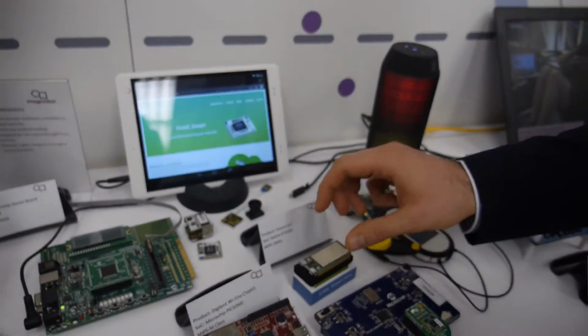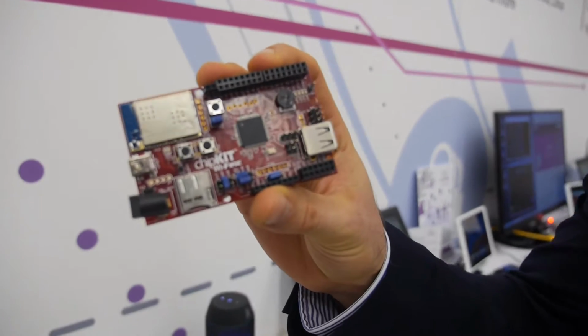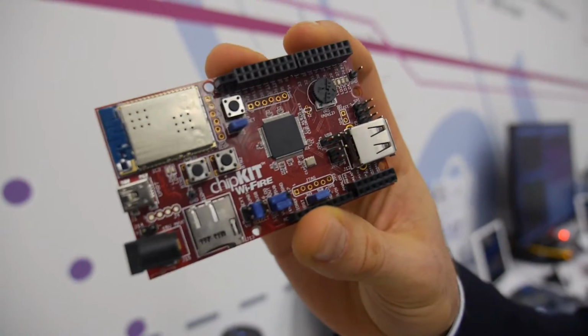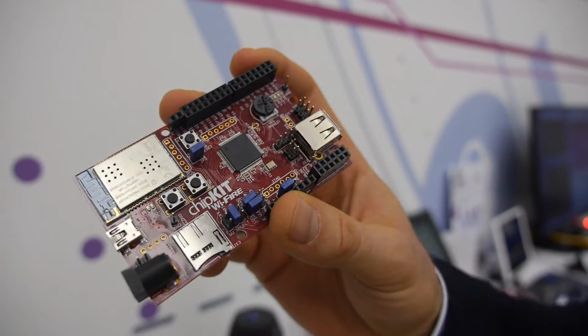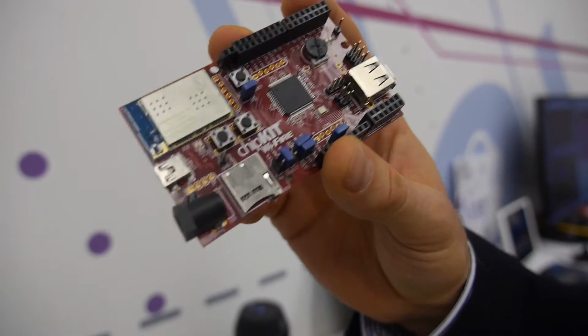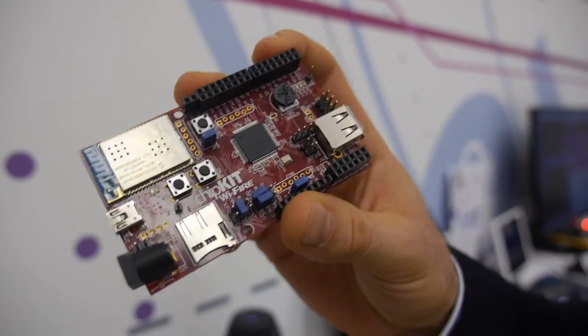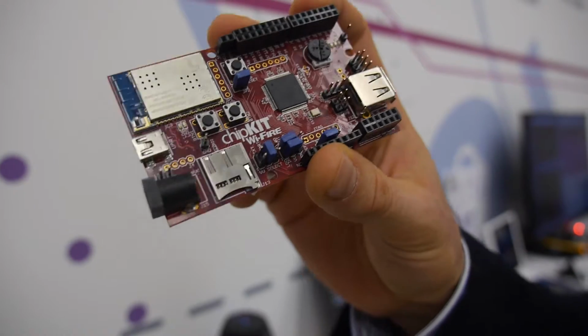We also have Qualcomm that uses MIPS. So their latest chipset is being shown here at the event running the Weave protocol from Google, and obviously Microchip, as I was mentioning, this particular board is using our M class. So M class is our microcontroller class MIPS processor. The unique thing about our M class is the ability to support hardware virtualization. So being able to run up to 7 virtual machines on the same microcontroller.